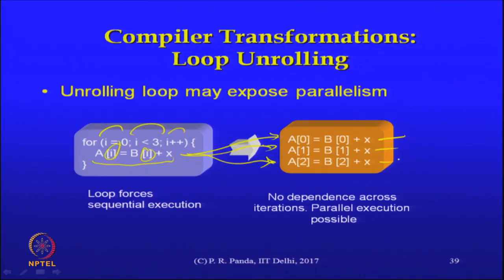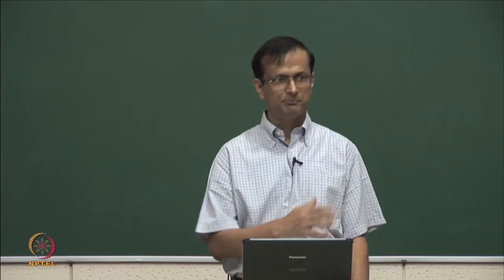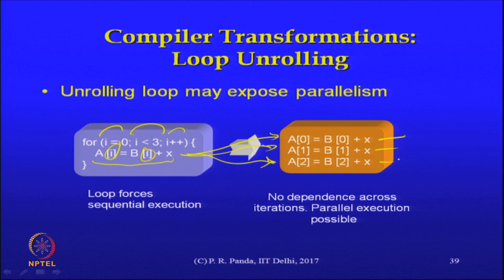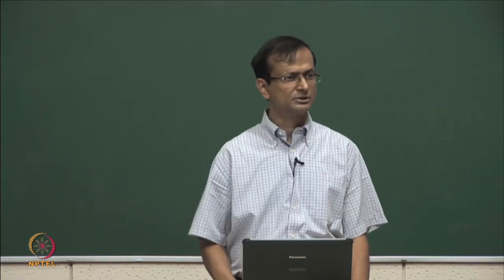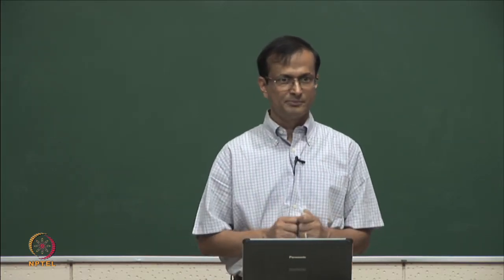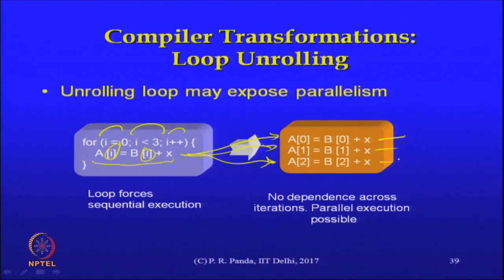But in general, this is a fine argument, where you can go to this extreme where everything is inferred as discrete components. You could also say that I have something like a platform that I have already defined parts of, which may mean maybe I have a register file, I have some definition of a bus, I have some processor components and so on. I fix part of it, but the other part that is not fixed is what is getting inferred by the synthesis tool.